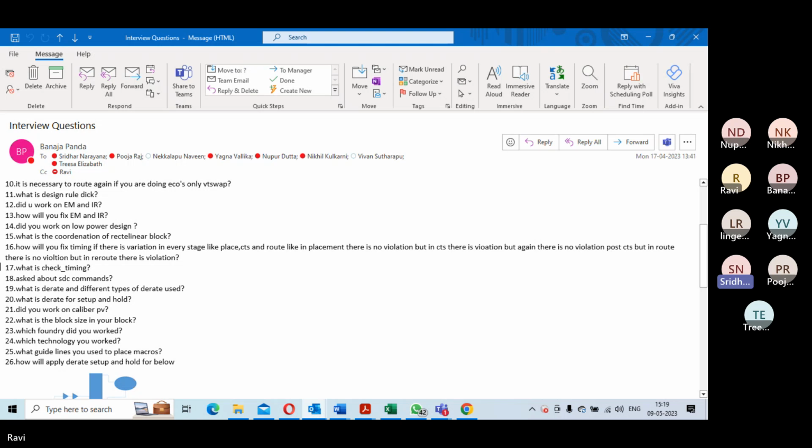Whenever we shield the interconnects with a protective layer, it will reduce the impact of electromigration, right? No. I told you, electromigration is a current density problem. By shielding the nets which are close by, they have no role to play in the electrons flowing through that net. We can add guard rings. Guard rings also no. How will a guard ring help?